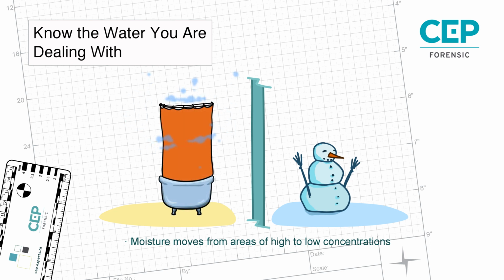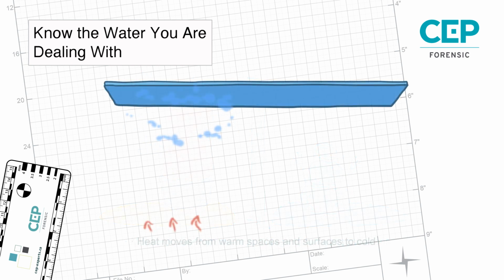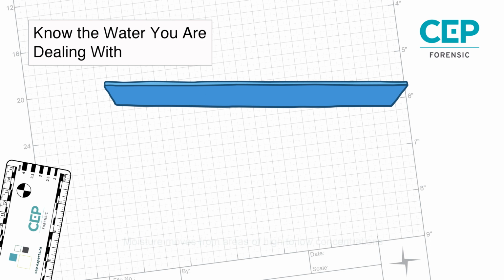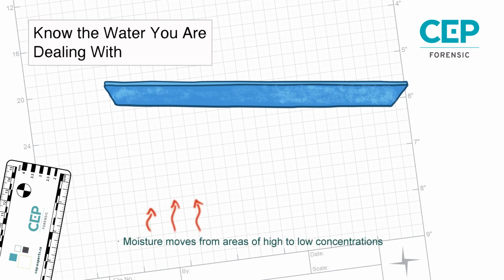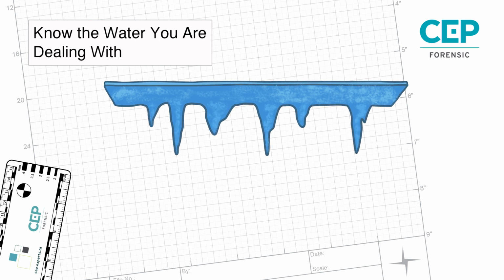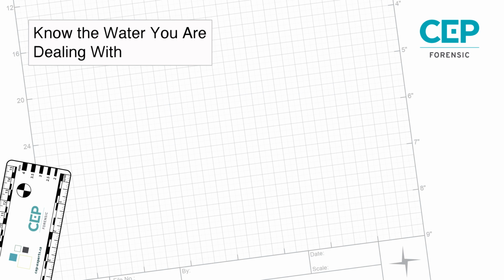As warm, humid air comes into contact with a cold surface, water forms. The resulting damage is often perceived as water leakage, but is actually condensation. Condensation often develops on window surfaces, but can also form in attics and exterior wall assemblies, causing mold, rot, and structural decay. While condensation can occur in both summer and winter, this phenomenon is more frequent during our cold Canadian winters.